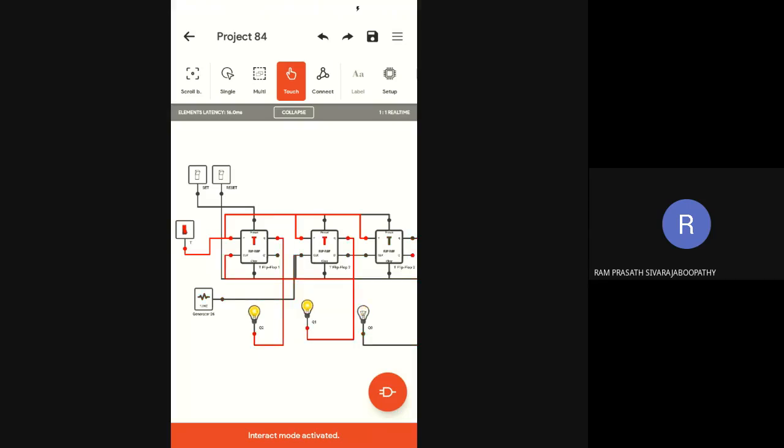See, this is for a ripple counter only. See, each flip flop is giving a ripple output to the next flip flop as a clock. Ripple means we take one output and give it as a clock to another flip flop, that we call ripple. See, the output of one flip flop is working as a clock to the next flip flop. That is why we call it asynchronous. Here there is no synchronous. Did I give a common clock to all the flip flops? No. Only the LSB flip flop gets the clock. So this is asynchronous. Clear? I hope everyone understands this. Okay. Fine.